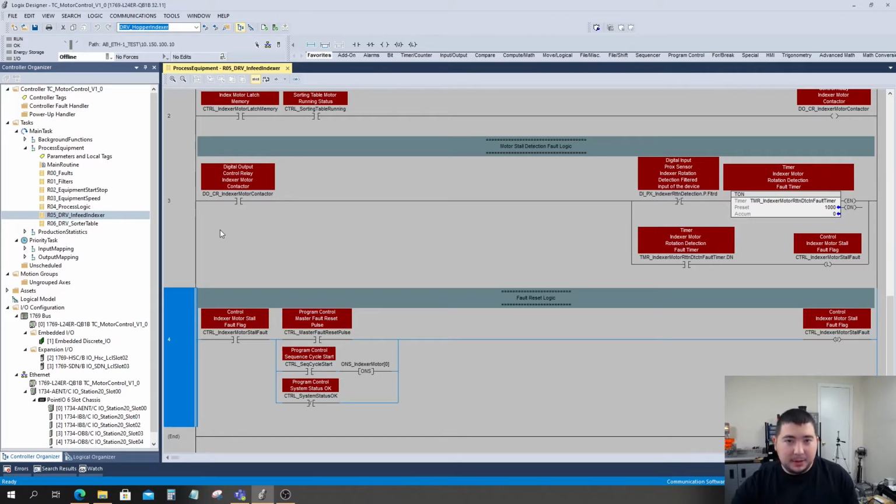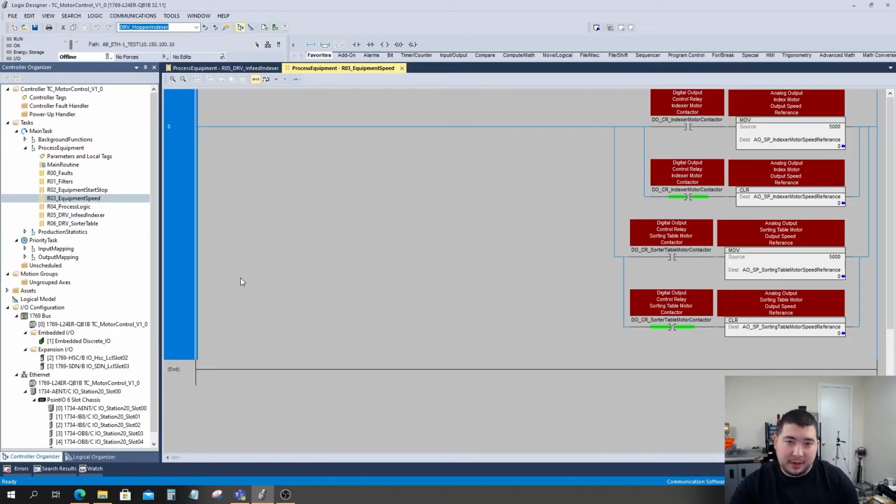So in the program, we can just simply create an equation which will perform this operation internally. In RSLogix 500, if anybody that's watching this has used that before, we used to have a function called SCP. This was a function block which essentially did a linear equation internally. It was on its own a y equals mx plus b equation.